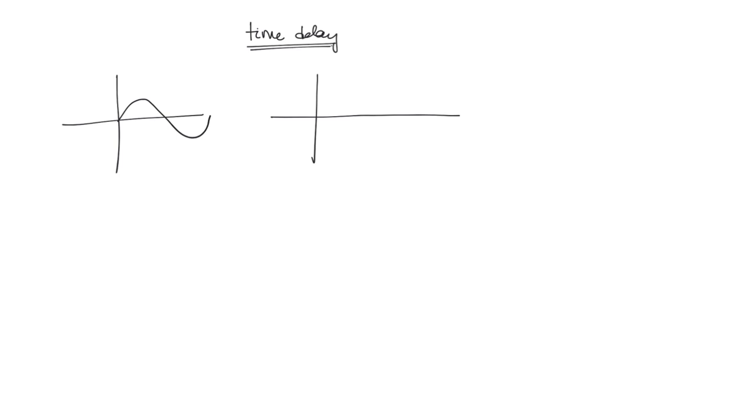Next we are going to discuss the systems which have a time delay. So how will a time delay model look? Time delay is nothing but, if a signal is starting from 0, let us say, then if there is a t0 seconds delay, it will start after t0 seconds. Right? That's all, nothing else. So in the transfer function, how will you model this time delay?